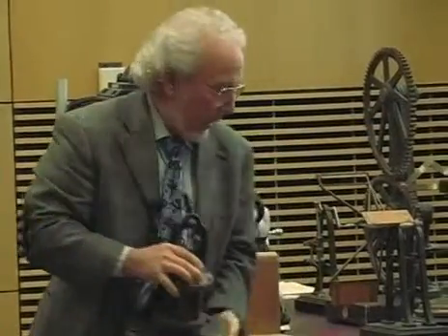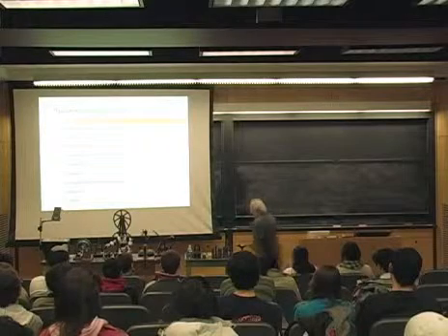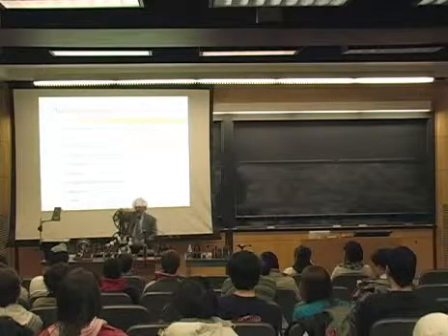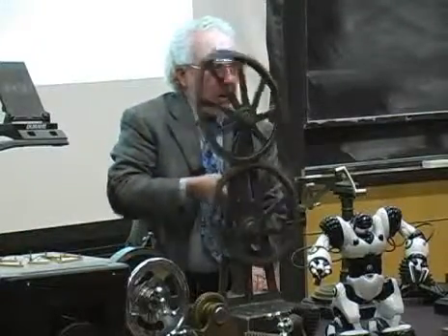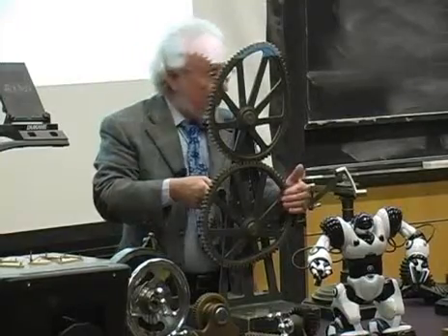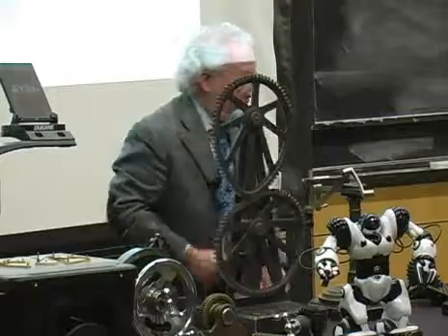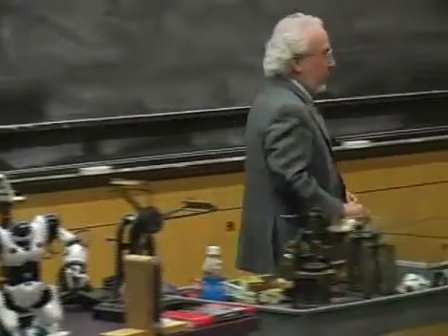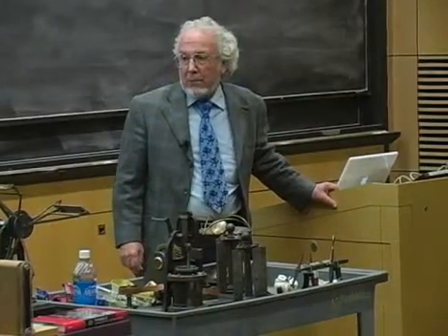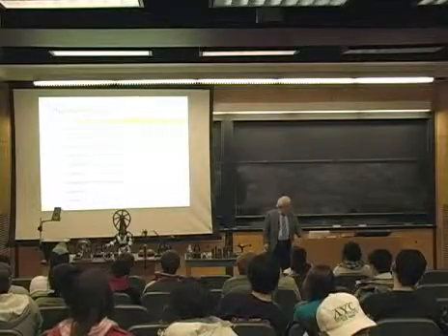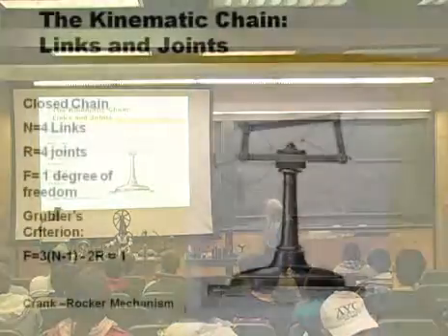So it's a surface constraint. On the other hand, if we talk about gears, so if we talk about a pair of gears here, the contact between the two bodies is either on a line or a point. All right, so each of these joints can be thought of then as a geometric constraint on the motion of one relative to the other.